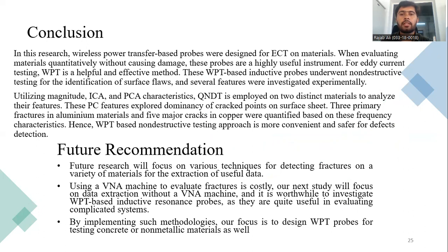These wireless power transmission based inductive probes underwent non-destructive testing for identification of surface flaws, and several features were investigated experimentally. Utilizing magnitude, ICA, and PCA characteristics, quantitative non-destructive testing is employed on different materials to analyze their features.